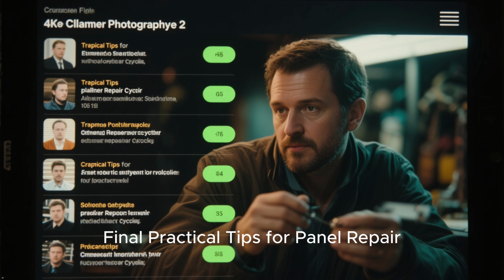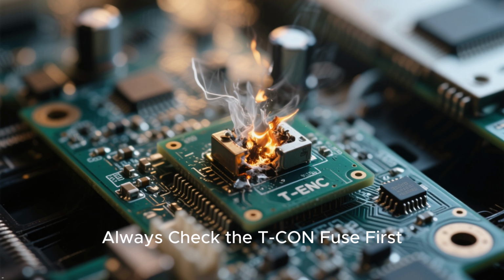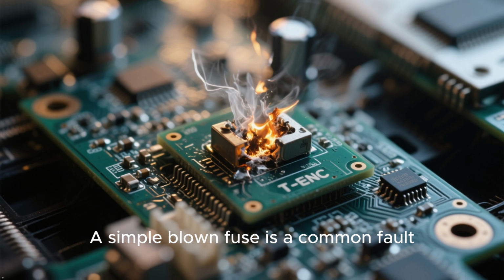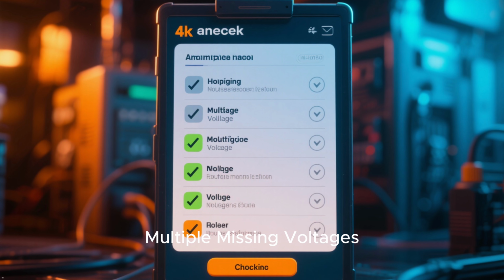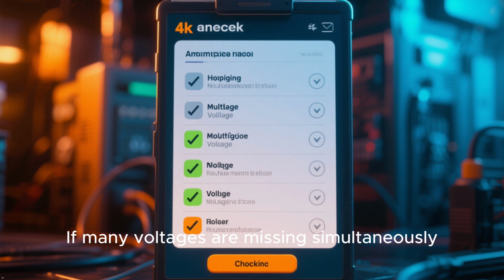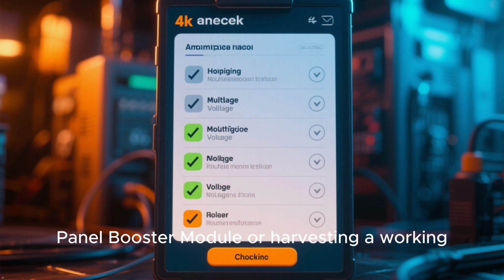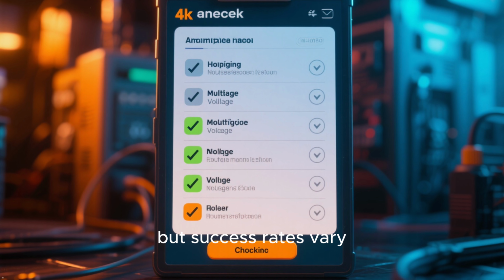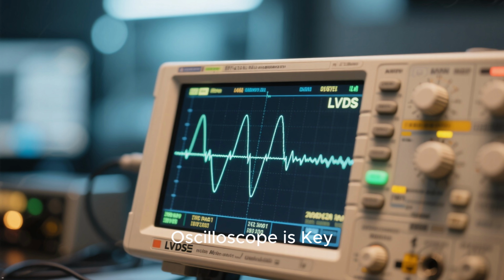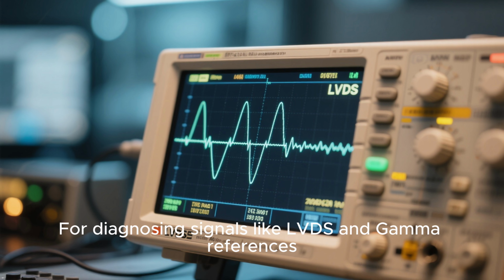Final practical tips for panel repair. Always check the T-con fuse first. A simple blown fuse is a common fault. Multiple missing voltages: if many voltages are missing simultaneously, you can try using an external panel booster module or harvesting a working T-con from a similar broken panel, but success rates vary. An oscilloscope is key for diagnosing signals like LVDS and gamma references.